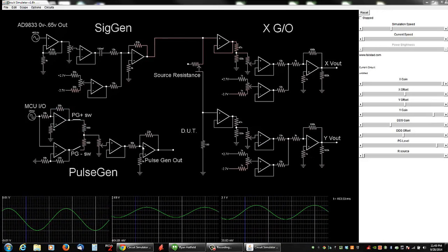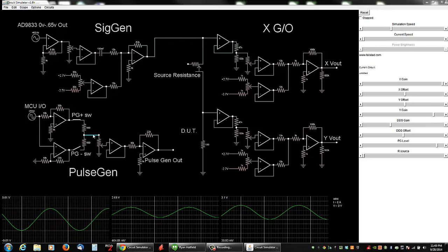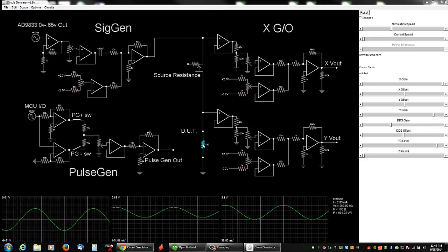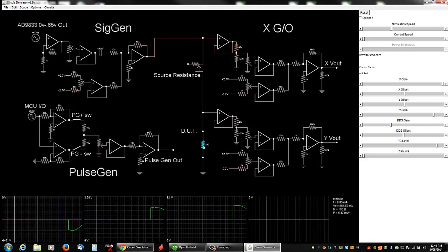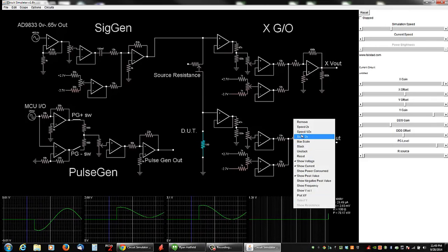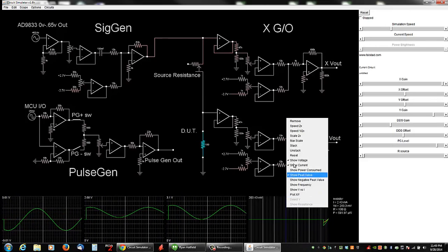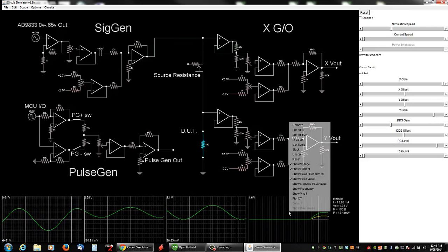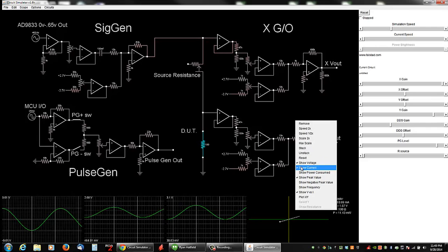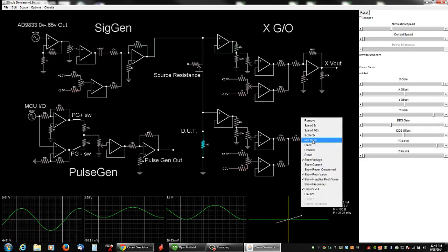And I'm going to ignore the pulse generator side of things for now, because with this simulator it just doesn't quite work right. So anyways, I'm going to go ahead and view the device under test in the scope. Again, I've got to speed this up a little bit, only because the settings aren't saved; between runs they change all the time. So I'm going to plot V versus I. I'm not going to show the current. Show negative peak value, and I'm going to maximum scale that.